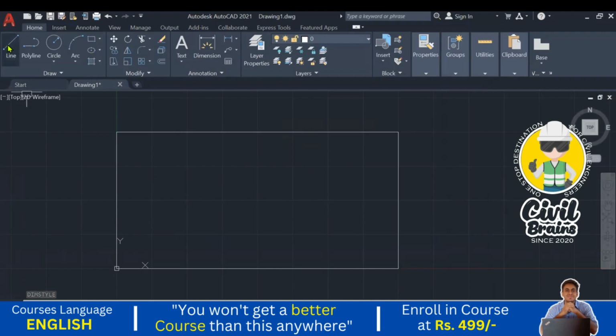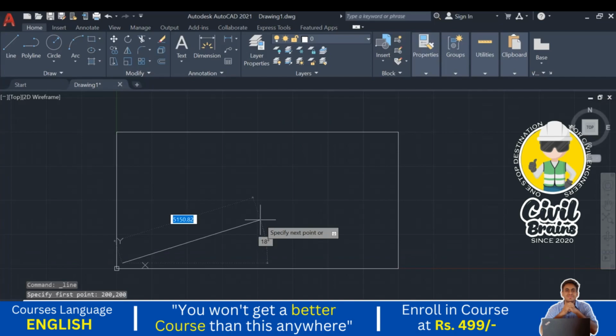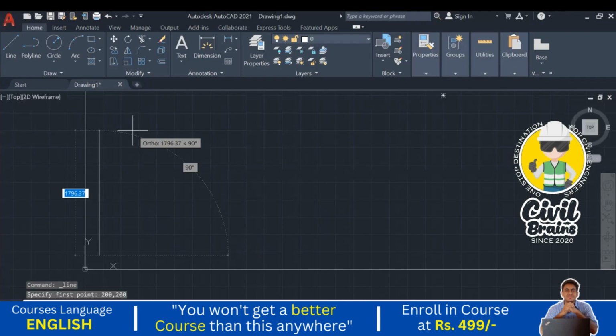So we'll start with the coordinate system. We'll go to the line command. Specify the first point. What is our first point? That is 200, 200. The first coordinate we need to type here is 200 by 200. Press enter. What is our next coordinate?